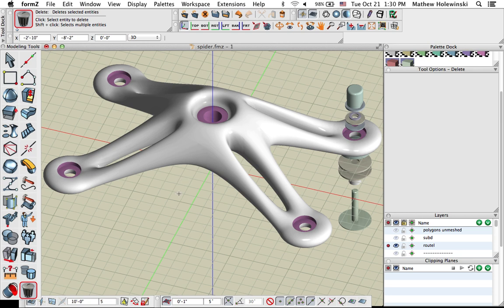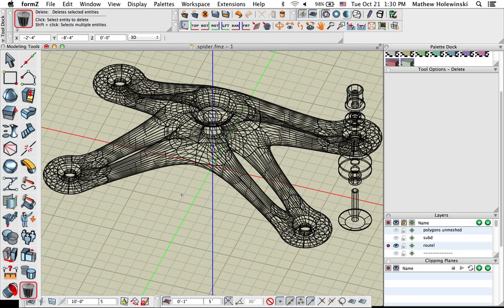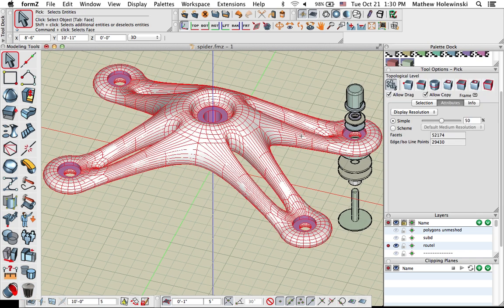Now, of course, because this is NURBS, when we're ready for the 3D printing process, I would just like to go through again and say that I would have to go into the attributes, display resolution, and control the faceting, so that when you export that out to STL or convert it to a faceted, the number of facets will be determined here, just as a reminder.